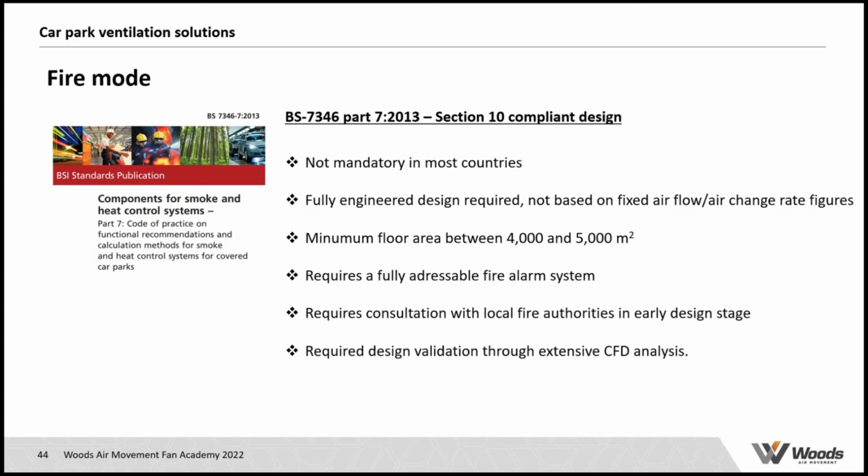So when you do a Section 10 design, the Section 10 design should always be based on 2 scenarios, which could mean that you would have to have a reversible system, because the one entrance is on the one side, and the other entrance they might use is on the other side. Then obviously you need to be able to reverse the flows in the car park. So it's a fairly complicated design, and it requires full validation through